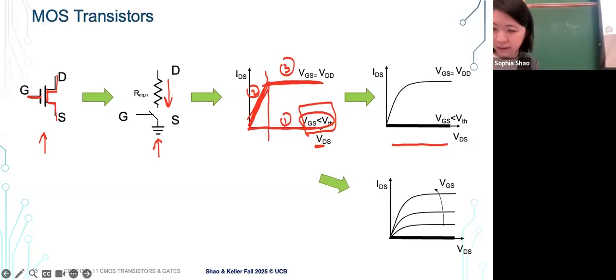So far the discussion has been about NMOS transistors, and of course, we can also modulate the gate voltage. Different gate voltages would lead to different channel behaviors, and that would make it act more like a variable resistor. With different gate voltages applied, you have different resistance of the channel here. Things make sense at a very high level, NMOS behaviors here?